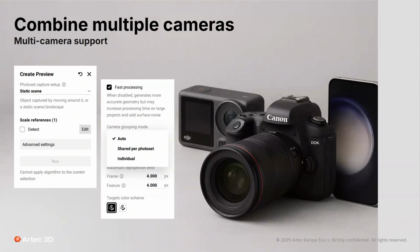And if you divide your photo sets by the camera, then you should select the shared per photo set mode. For instance, if you have one photo set from a drone and one photo set taken from the ground with a different camera, and you import them separately by dragging and dropping those folders which are divided, then it's best to select the shared per photo set mode.